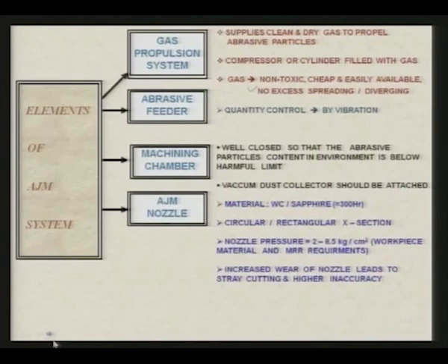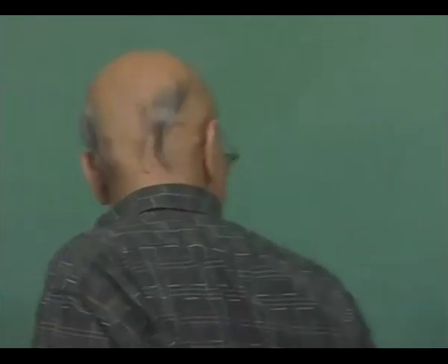Now, increased wear of the nozzle leads to stray cutting and higher inaccuracy. We should use a nozzle material such that the wear of the nozzle is minimal. If there is excess wear of the nozzle, then definitely you are not going to get an accurate workpiece, as I can just show you over here.